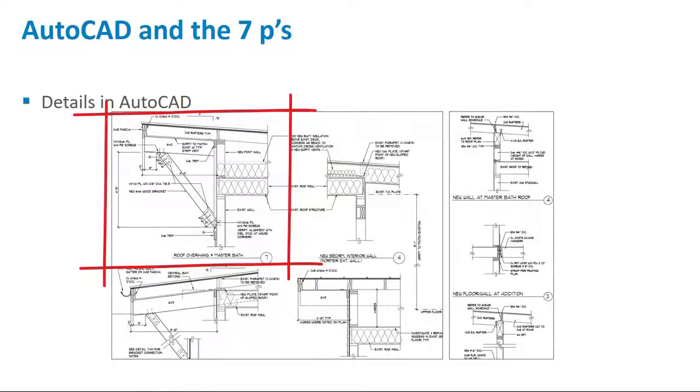You can see the timber sections where, at the moment, they're just lines. You'll probably start replacing those with Revit Families of yourself. So gradually you'll start switching over from a pure AutoCAD detail to something that's got Revit Families within it. So it can be a gradual process.